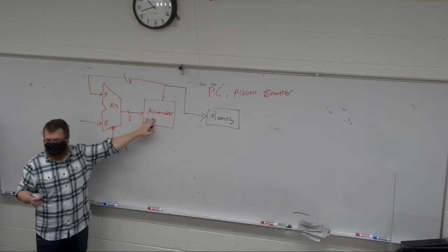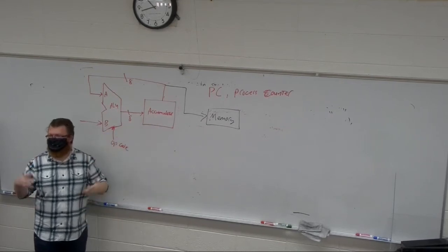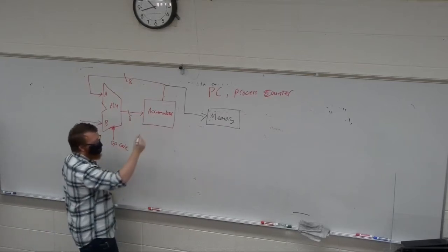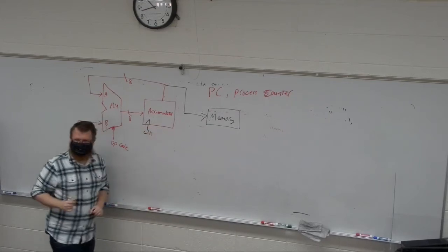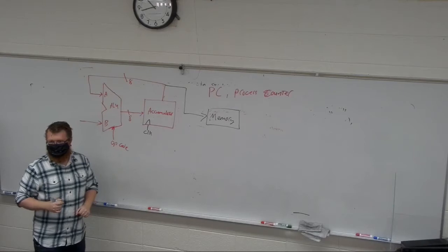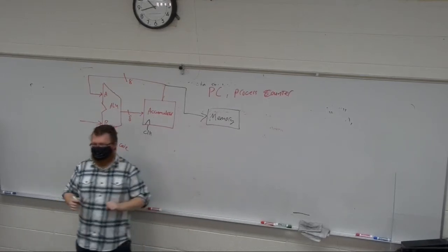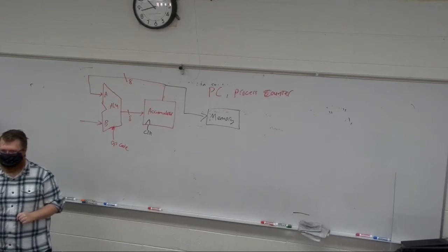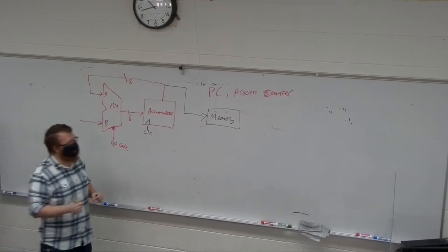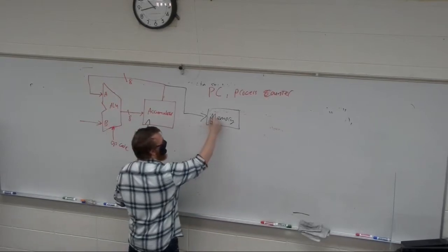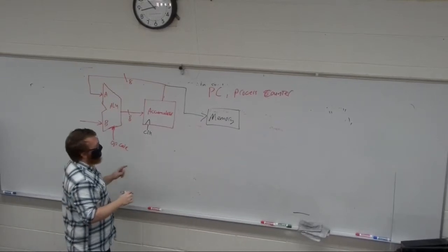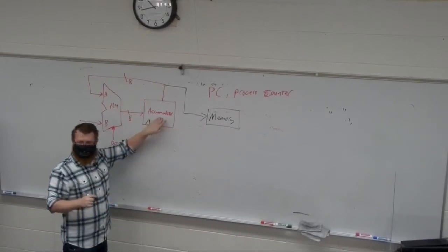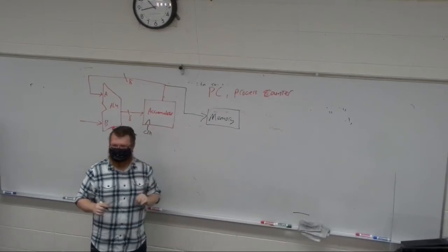The accumulator, sequential or combinational? Sequential. If it has memory, it is therefore sequential. Therefore, it needs a clock. The memory we may implement as clocked or not clocked. There are multiple ways to do this. If you clock it, which I think might actually be the easier way for you guys to think about the memory, you need to make sure that the change in the accumulator doesn't happen at the exact same time the change in the memory happens.